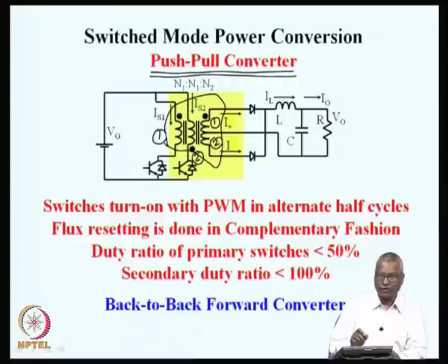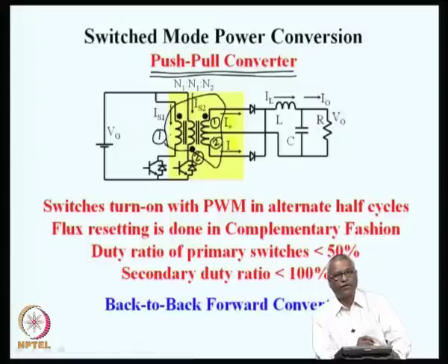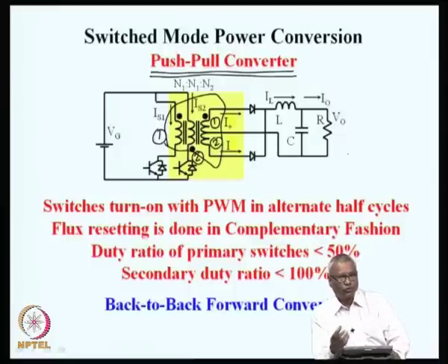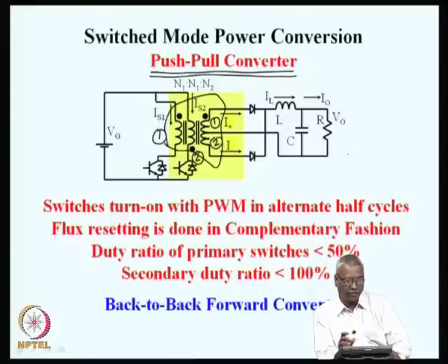Earlier we had a circuit where the positive part and winding 1 made the one forward converter, and here that is retained, and we have put one more winding and then a negative part of this here with respect to the center tap. So, effectively now two forward converters are integrated into a single magnetic element.